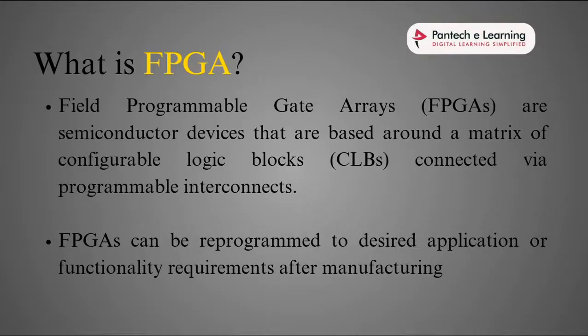Because you already followed the architecture, the processor core, and you designed the memory block, the RAM block, the MIPI interface, the modem. So you can't change anything. After completion of the chip, you can't change anything. If you made it with errors, bugs, then it is an error only. So it's a total cost waste. But an FPGA is not like that.